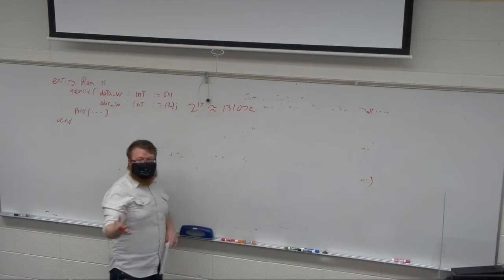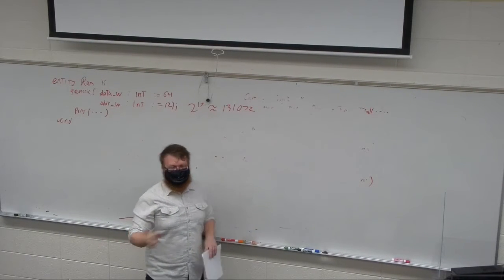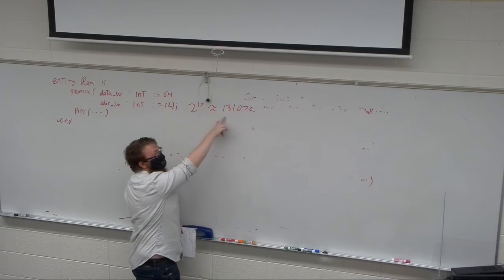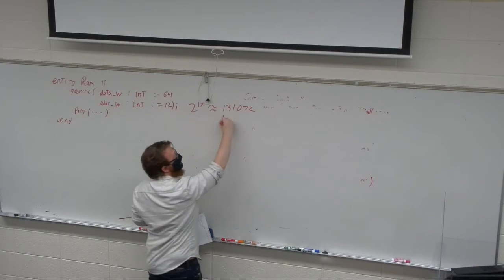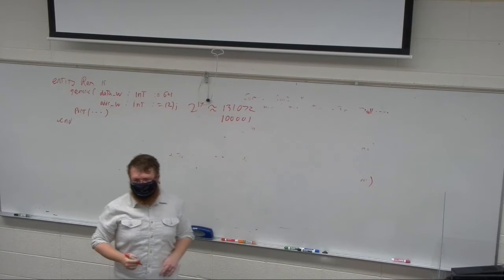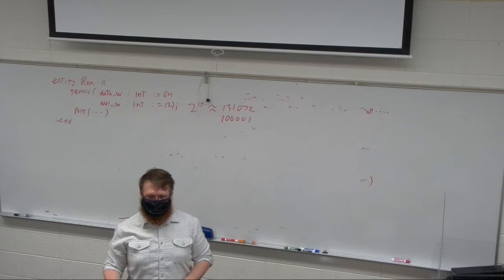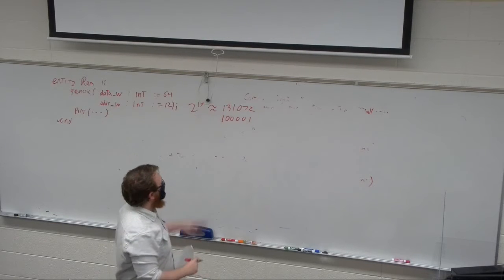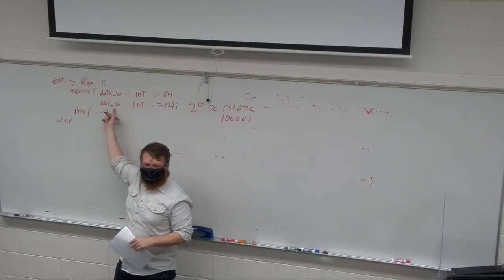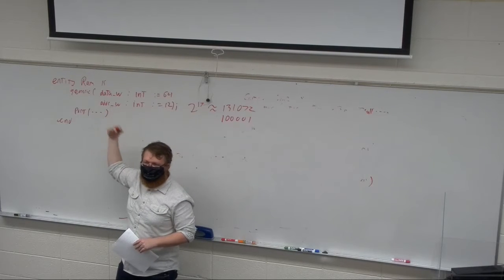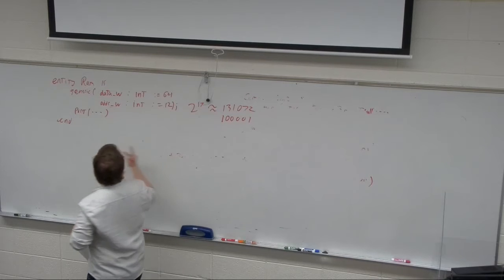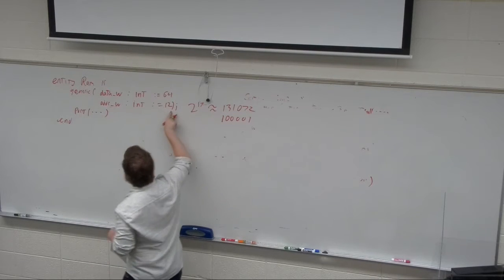So the issue you might have run into in your SPI is if you're trying to only go to 100,000 and you spill over to address 100,001, nothing's there. You initialize the values for the first 100,000 addresses, and the next one is just 0. This instantiation would avoid that, but you don't have a way of creating it with only 100,000. You have to create it with powers of 2. So here, for your case, you would just say 17.